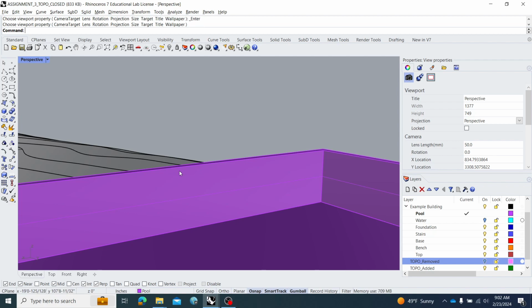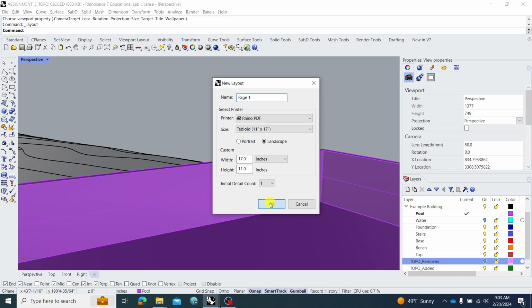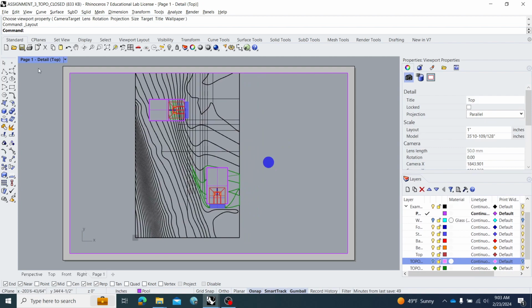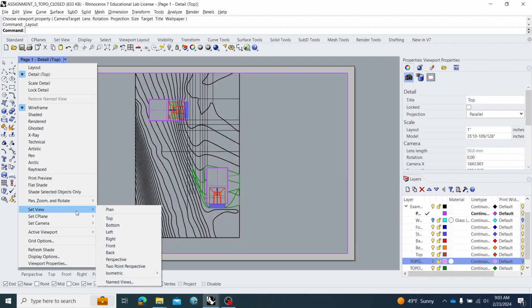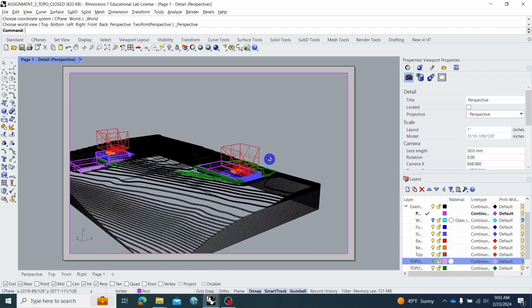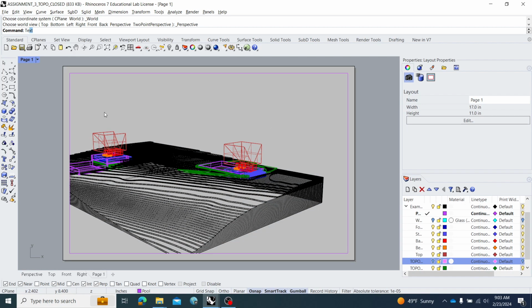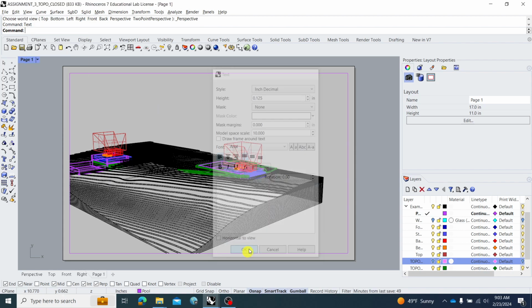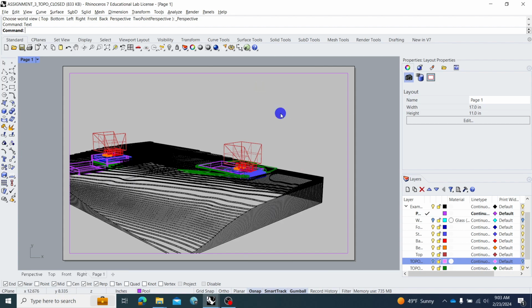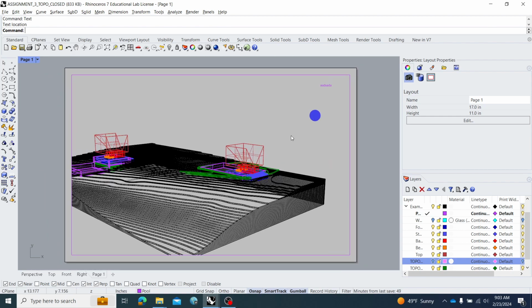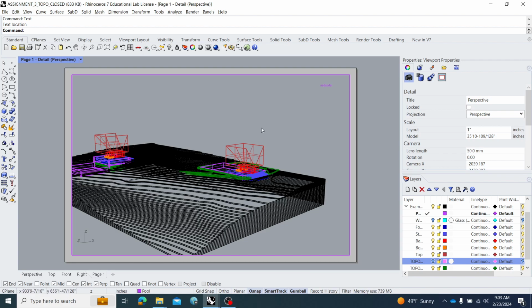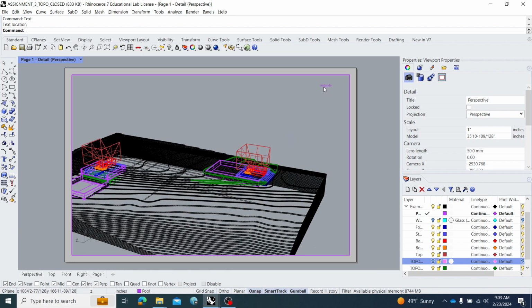Again, make sure that everything is put on the layout tab. Creating a new layout, for instance. And we can save that as it is. Make sure you have your text by writing text. And make sure that this text is on the layout tab and not the workspace. How we can tell is if we activate the workspace, which I just did by double clicking. If we rotate this, the text does not move, which is what we want.